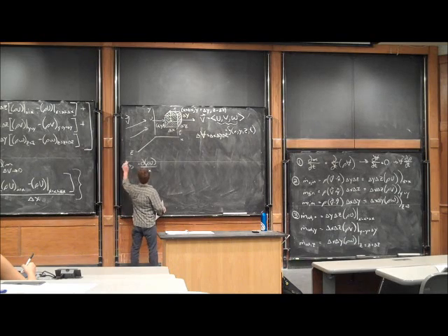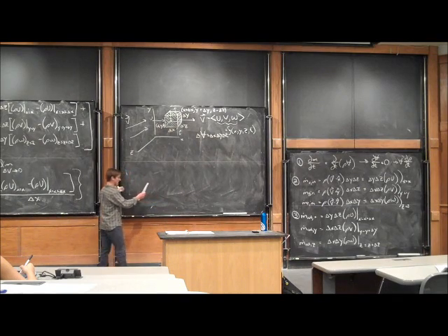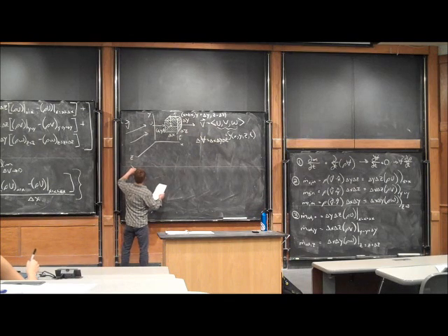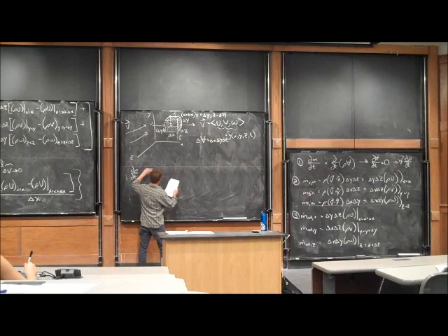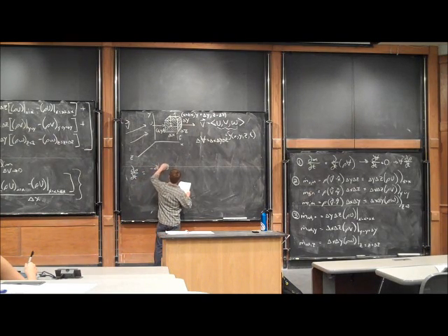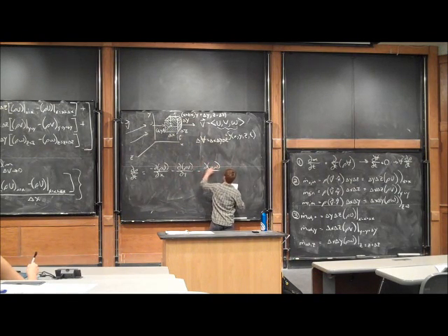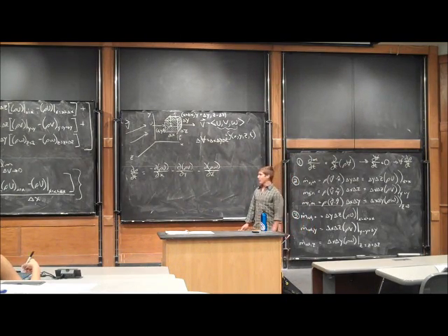So now our entire conservation of mass equation is to be the change of mass coming into the system. I get del rho del t is equal to negative del rho u del x minus del rho v del y minus del rho w del z. Does everyone follow me before we are here? This is a big step. This is pretty important.